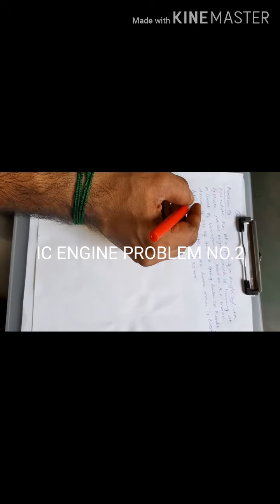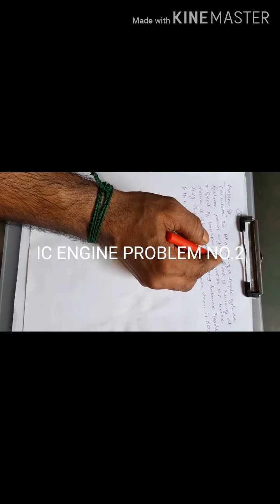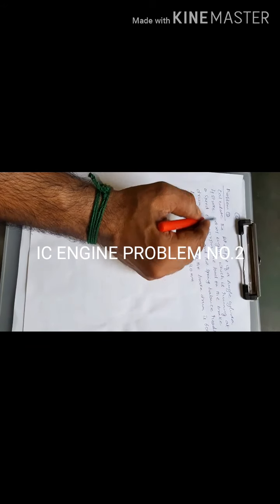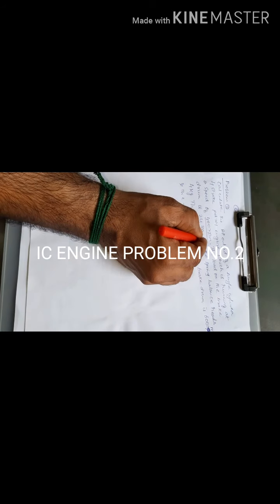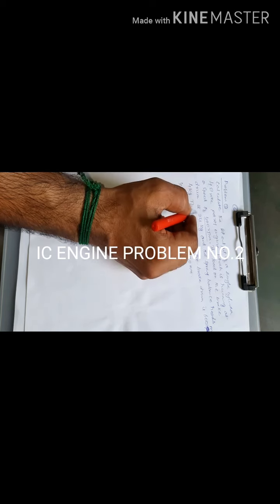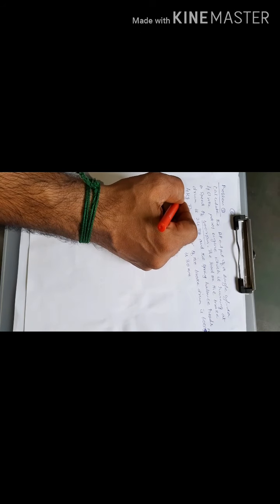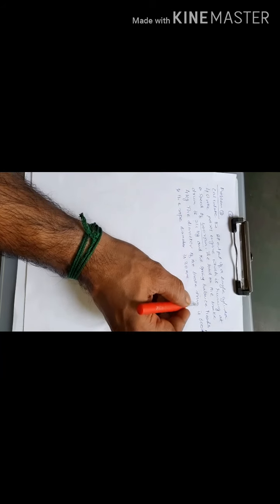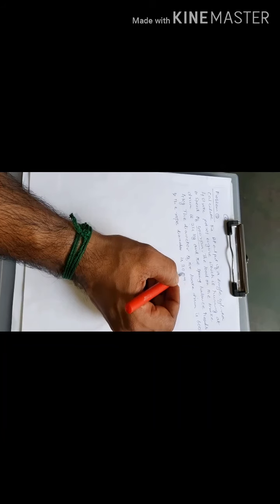Now we go for the second problem. In this second problem, calculate the brake power output of a single cylinder 4-stroke petrol engine which is running at a speed of 400 rpm. The load on the brake drum is 24 kg and the spring balance reads 4 kg. The diameter of the brake drum is 600 mm and the rope diameter is 30 mm. So this is the problem.